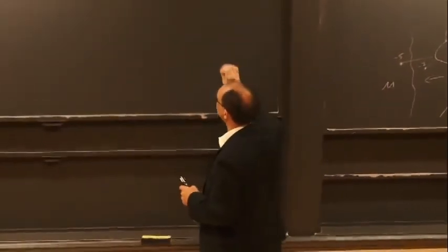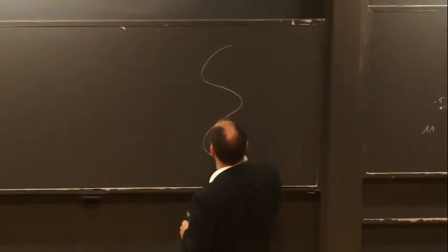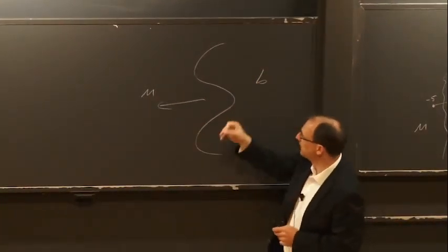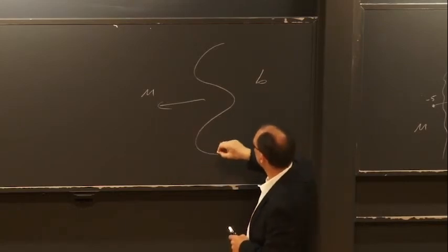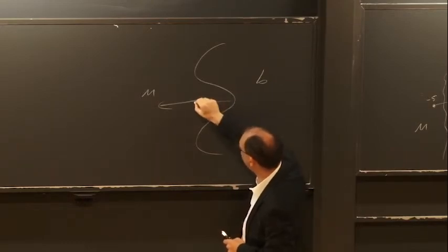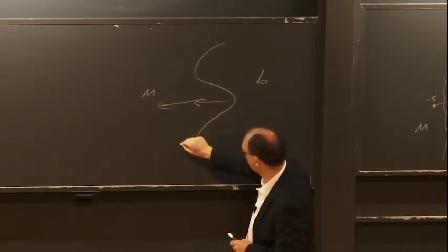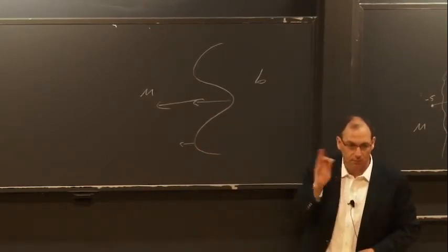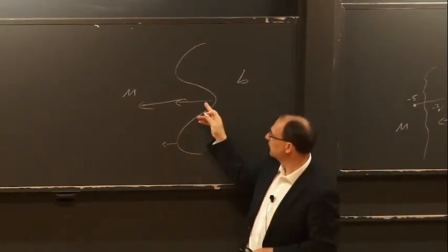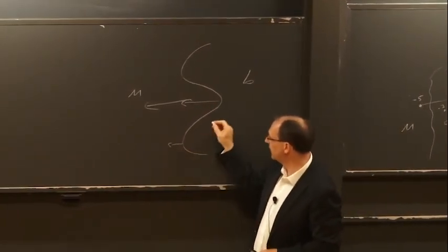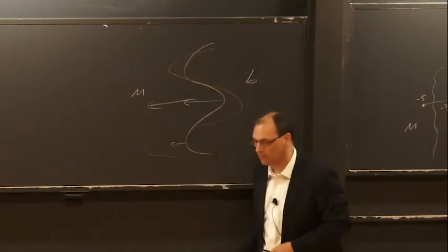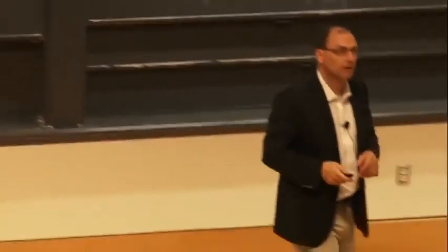So if you look at this, a flame like this, this is unburned, this is burnt, and it propagates in this direction, as we'll see later on. Then it turns out in these regions here, the burning velocity will be faster, and in this region here, it will be slower. There's a stabilizing effect that takes out these curvature effects. The opposite is the case for negative Markstein number. These here will be slower, these will be faster, so this thing will, after a while, look like this and it will become unstable. We'll talk about the instabilities in a minute.